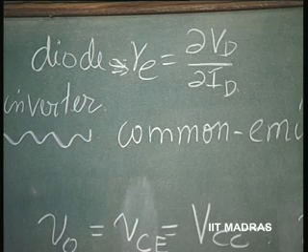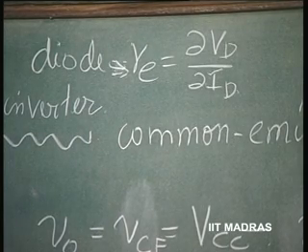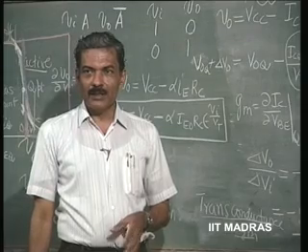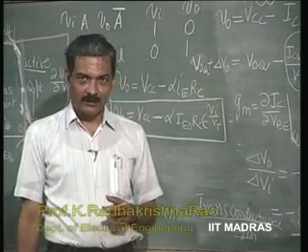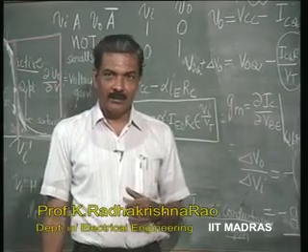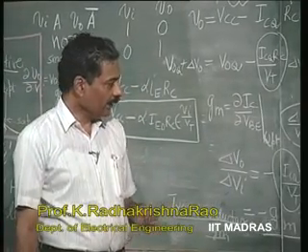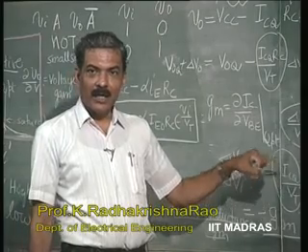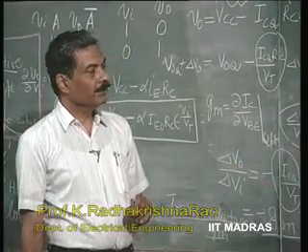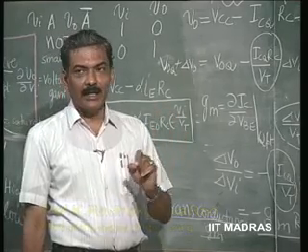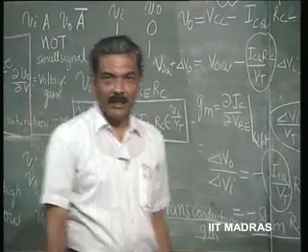So, GM of a transistor is almost nearly 1 over Re, or strictly speaking it is alpha over Re, slightly less than 1 over Re because of the factor alpha. So, GM of a transistor is alpha divided by Re, where Re is delta V diode by delta I diode. In this case delta VBE divided by delta IE.